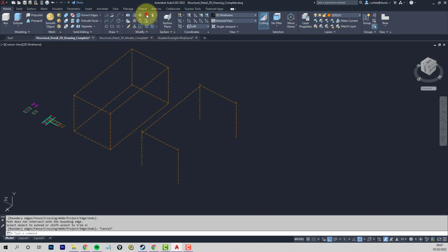All we need to do now is copy that across to the other side. So copy, endpoint to endpoint. Now because that's actually a line, we could even offset it. Let's just see if that works. If I go back to the world coordinate system and use offset of 3000, it should end up on this side because it's still just a simple line. So offset is here, distance 3000, and there you go. So you've got that advantage of it being just simple lines that you can still use 2D commands even though it's floating in midair now.